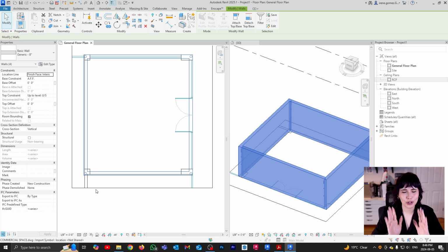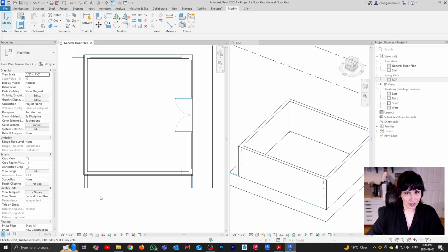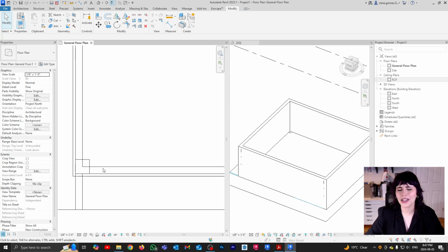This is super important. I've seen this in real life and I have a mini stroke whenever I see it. In construction documentation, there is no such thing as good enough. There is no such thing as, yes, the wall is thick enough for the drawing. No. If the reference tells you a thickness, your wall has to be that thickness. It is not optional, okay? So it is very important that the thickness of my Revit wall matches the thickness of my reference.